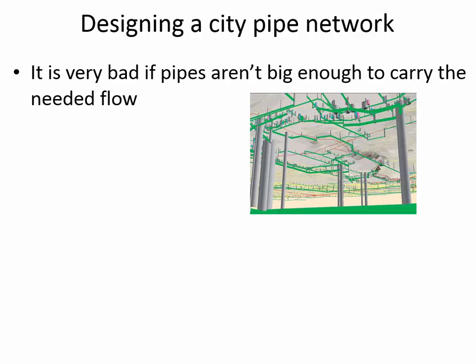And so if you have a small diameter pipe, then that's going to have a small D, which is in the denominator, and the cross-sectional area will be small. And since both of those are in the denominator of the Darcy-Weisbach equation, that means that you're going to have a lot of head loss. And so all of that energy that you gained by putting the reservoir up on the hill, you'll just be losing it due to losses, and then there won't be enough pressure left at the home. And so people will open up the tap and it'll just be a trickle.